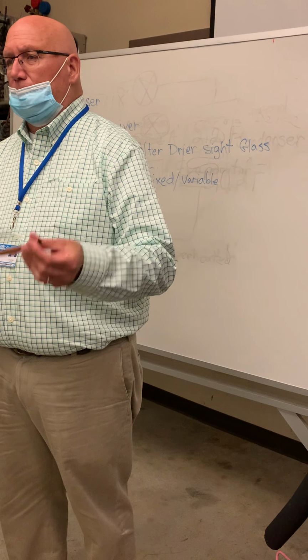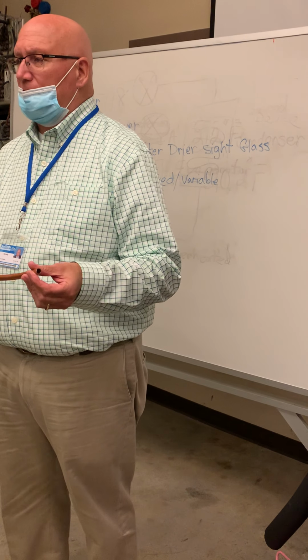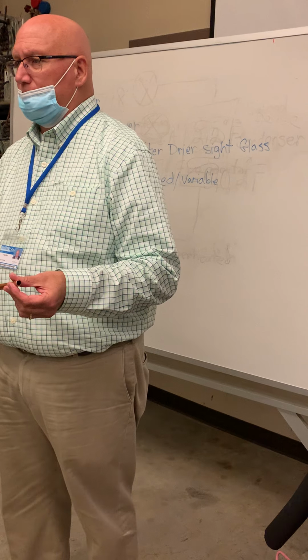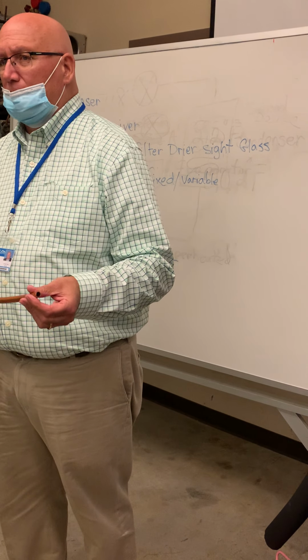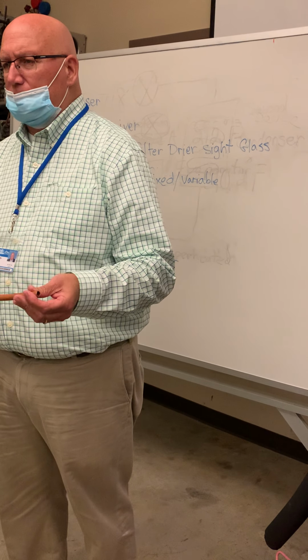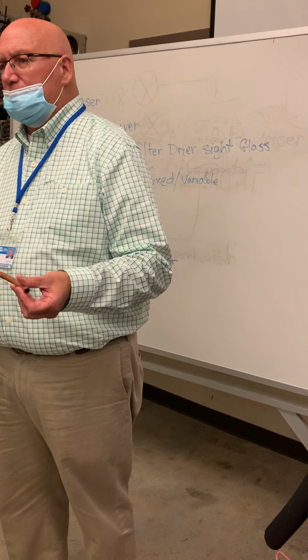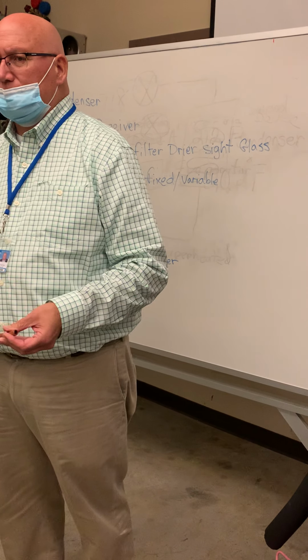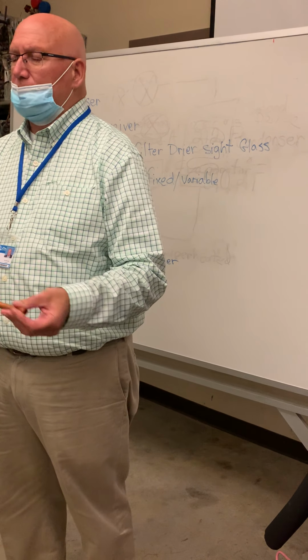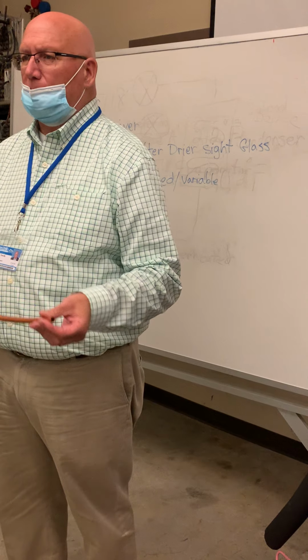So if you have 25 extra feet of liquid line, that would mean that unit that had 7 pounds of refrigerant now requires 7 pounds and 25 ounces. And you can do the conversion for the math for the pounds.